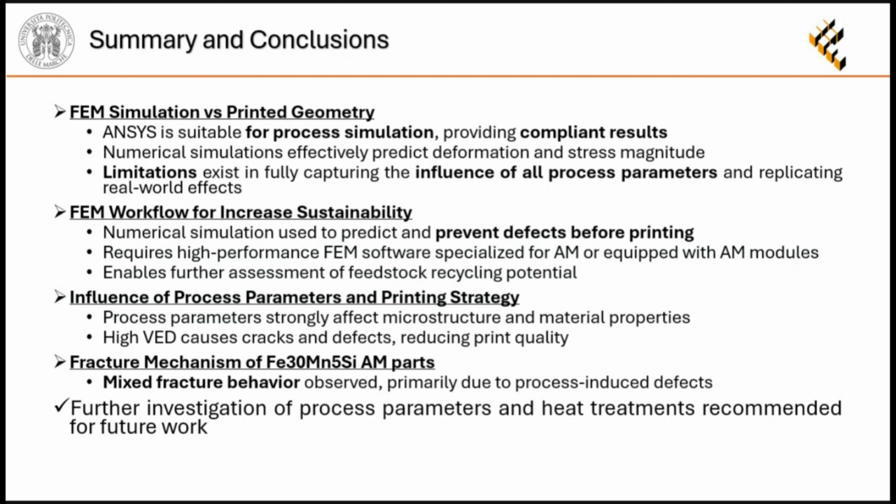of the process. Also, we observe the influence of process parameters and printing strategy that may cause several defects due to the high volumetric energy density. And also we observe the mechanism for the mixed fracture behavior of the iron, manganese, silicon additive manufactured parts, which is caused by the process-induced defects.